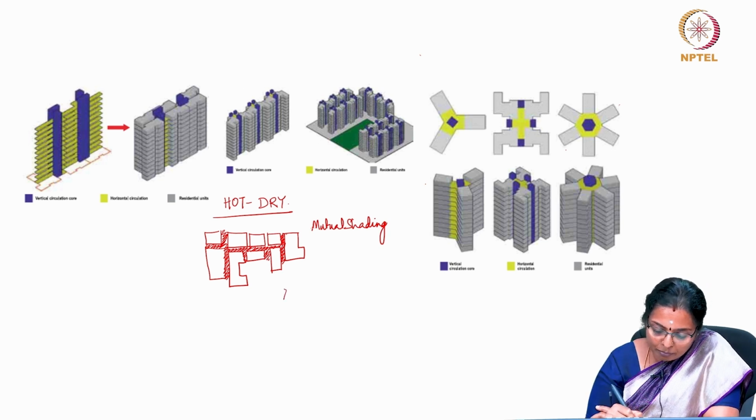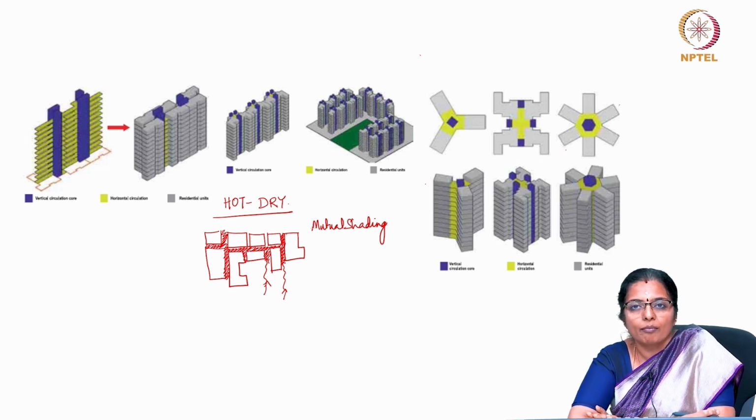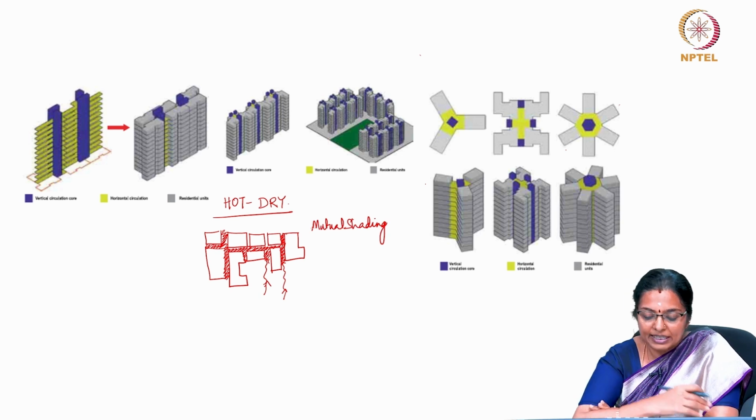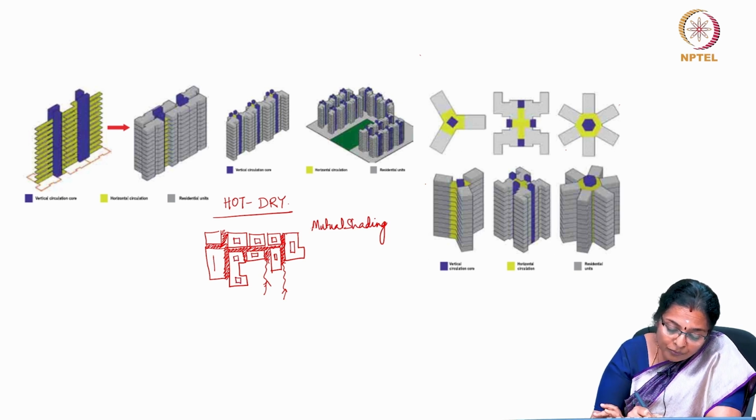If there is a wind direction, then we must promote this wind because it will get promoted because of the channel effect or tunnel effect. Include small enclosed courtyards with arcades and colonnades for light and air and outside day-to-day activities. So, if you think the house will get too congested, provide for a small courtyard in the house so that the house is well lit. Also, this can serve for good ventilation,